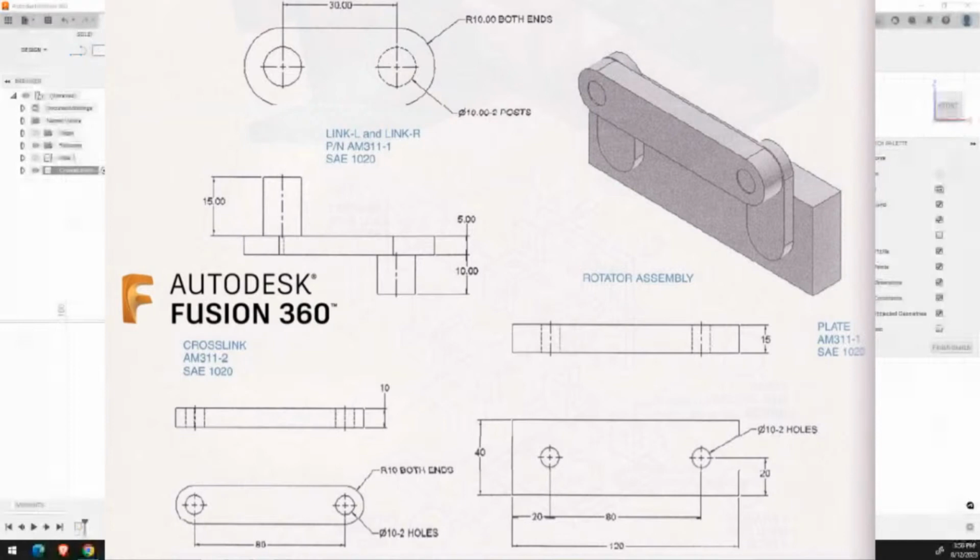But before you finish your sketch, make sure that it's fully constrained. If it's still blue when you make it 3D, it may still move. Even in 3D, we can still move it. To be sure, and for safety, proceed only if your object is black or fully defined. Okay?